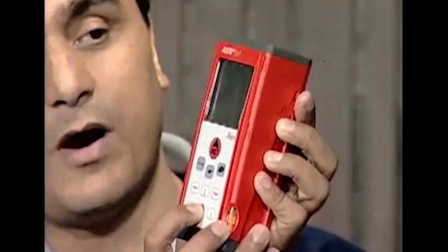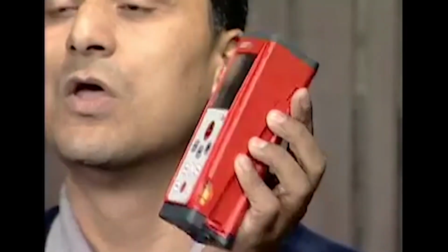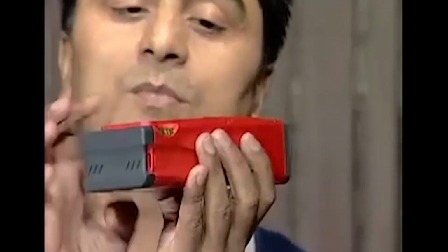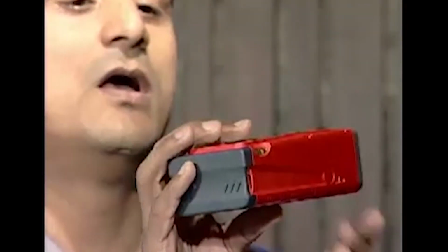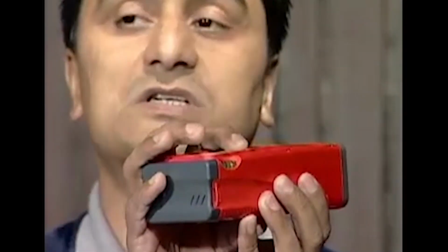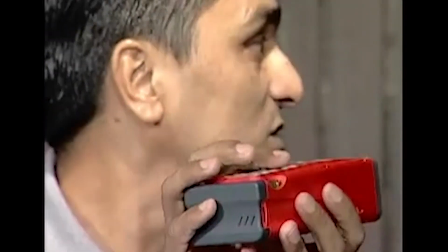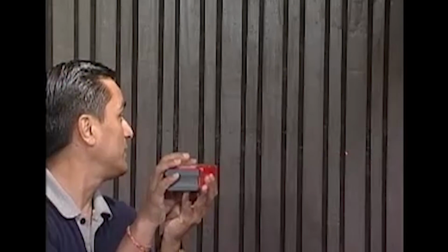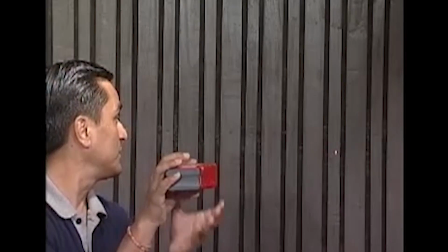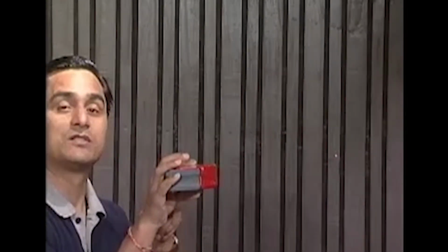What you need to do here, you just need to switch it on, and here is the power switch. It gets switched on, and then you point it. For example, I am pointing it to the wall here. If I point it to the point where I need to measure the distance, then I ask for the distance. As you can see the red dot here. This red dot means the laser pulse is being fired there and is reaching that particular point and is being reflected from there. Again, after it is being reflected from there, it is coming to the instrument. The instrument is capturing it back, and then it gives me the distance. It tells me, okay, the distance is 1.56 meters.